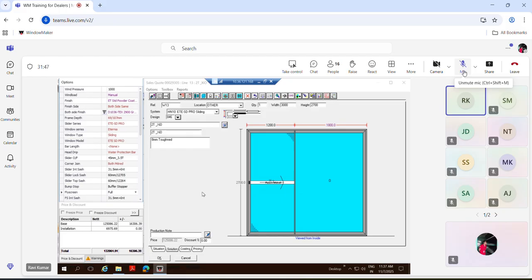Also, the maximum glass thickness you can consider is 20 mm, in 5 mm, 6 mm, 8 mm, 12 mm, and 20 mm. 10 mm is not feasible in this series.